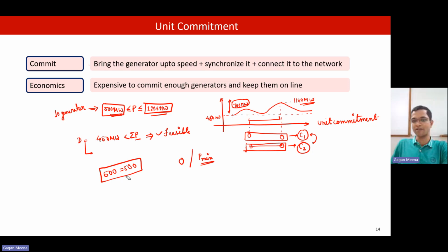because we have a constraint that all the generators need to run at least because they are on, and there is a constraint that Pi should be between P minimum and P max, and all the generators are on, then all the generators need to be at P min as per ED.